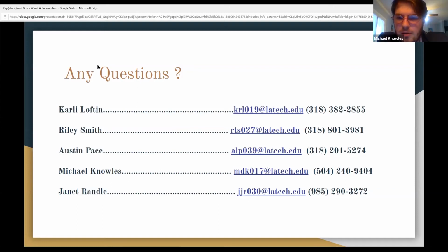As for the piles, the timber piles and the sheet piles are going to be delivered by truck. The steel piles will be delivered by barge. The steel piles are the ones that are going to go to the yard, and that has to go along with the owner operations of the project.